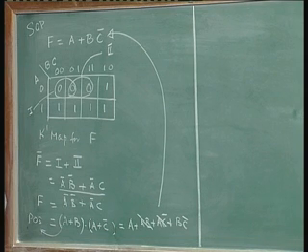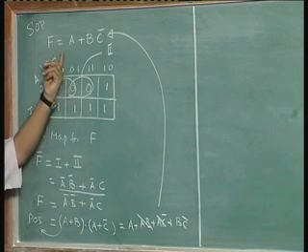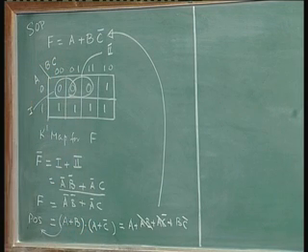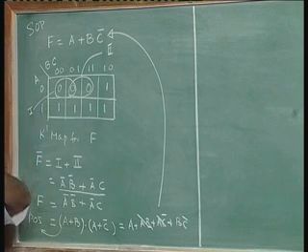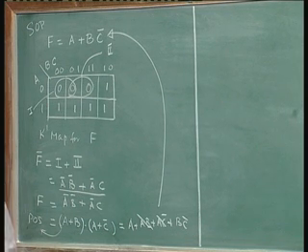Where will I use that situation? I will use the situation where I want to have OR gates feeding into an AND gate, because each sum term represents an OR gate, and each product term is an AND gate. Sum is equal to OR. Really no sum, it is an OR operator, because we put a plus, we call it sum. Plus is an OR operation, dot is an AND operation. So, a sum term represents an OR gate, a product term represents an AND gate.